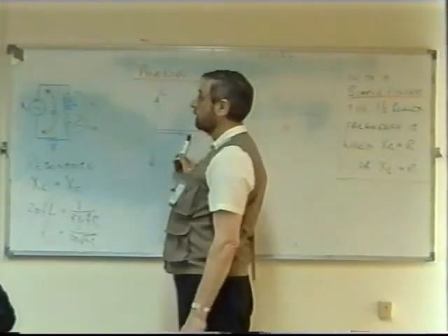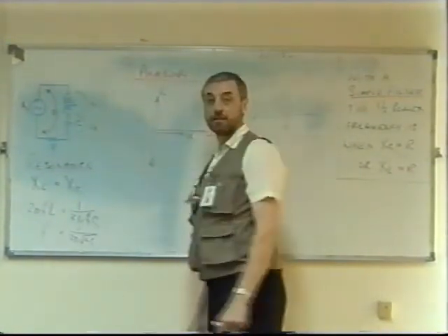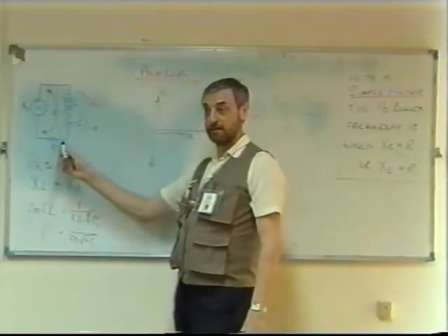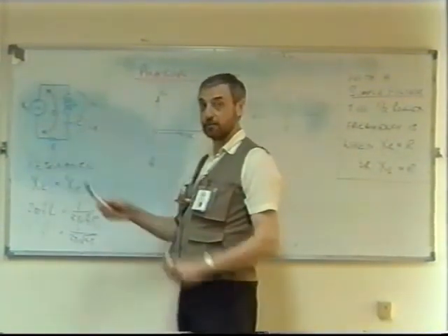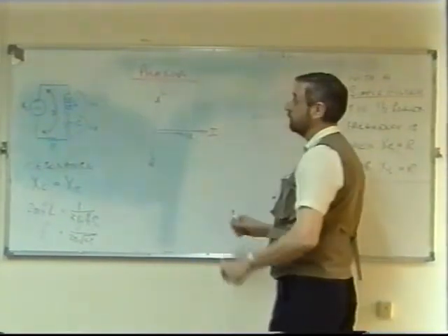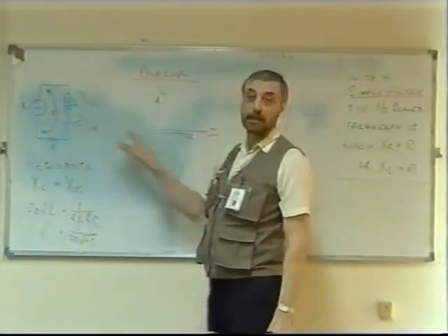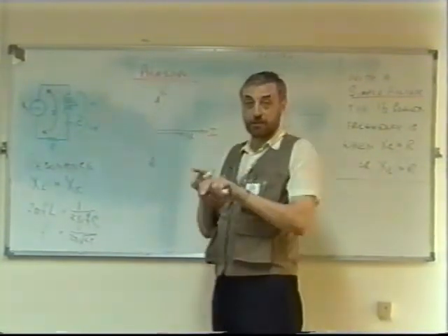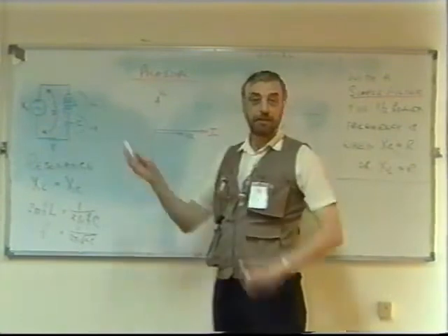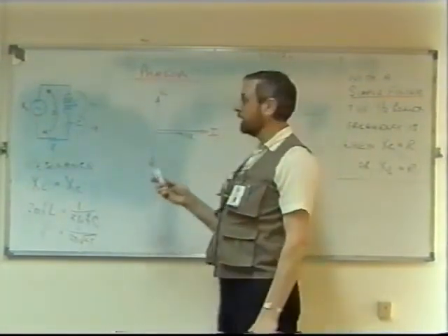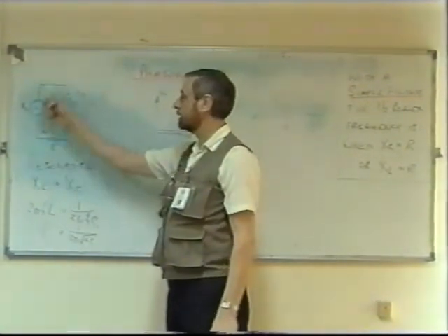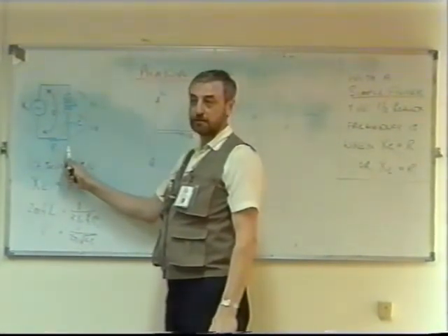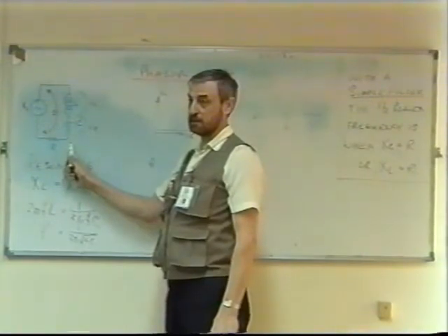So what is the total impedance of the circuit? Just R. Yes, just R, because the impedance of the circuit depends on XL, XC and R. But XL and XC produce back voltages which are opposing one another, so they cancel each other. So the only impedance in this circuit is just R, and the output will be in R.